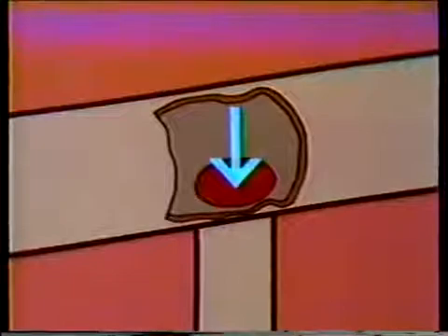In drum-type boilers, inspect the places where the downcomers are attached to the drum. Attachments should be checked for cracks, evidence of corrosion or erosion. Downcomers, which are pipes that carry water from the drum to the bottom of the furnace, generally have some kind of baffles at the top, called anti-swirl or anti-vortex baffles. These prevent water from swirling as it enters the downcomer. Downcomer baffles are built in 3 different ways. They may be crossed metal plates secured just inside the downcomers.